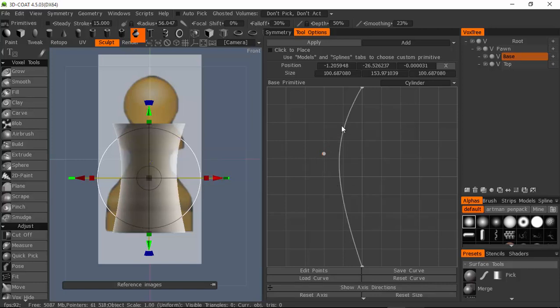You know it's a B-spline because the dot or the vertex is not on the line, and actually there's control parameters that you're not seeing right now. We could put them up there, but I'm not as worried about that. So sometimes you'll need to switch between those, so just know that I like soft curve for most of what I'm doing because it's more precise.